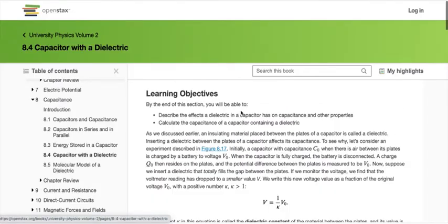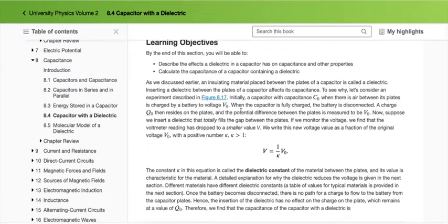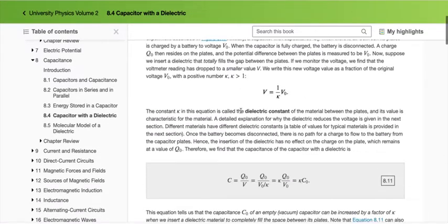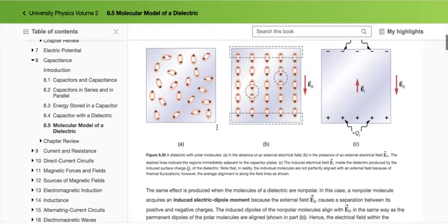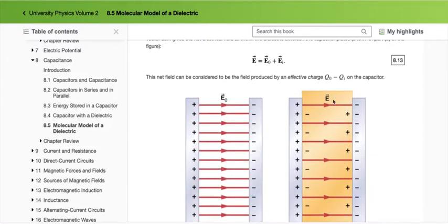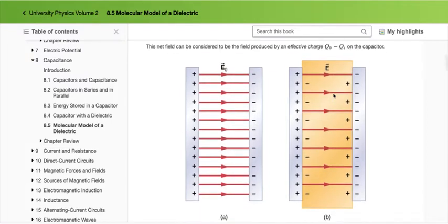Okay, now in the real world, we like our capacitors to be better. So what we'll do is, I think it's easier to start here. We'll put something inside our capacitor. We'll fill that area up with, instead of a vacuum, some kind of insulating material. And what happens is we get polarization. We get some drift charge floating around inside that insulating material, because we've got all these positives over on one side here. Some electrons will want to come over and hang out with those positives.